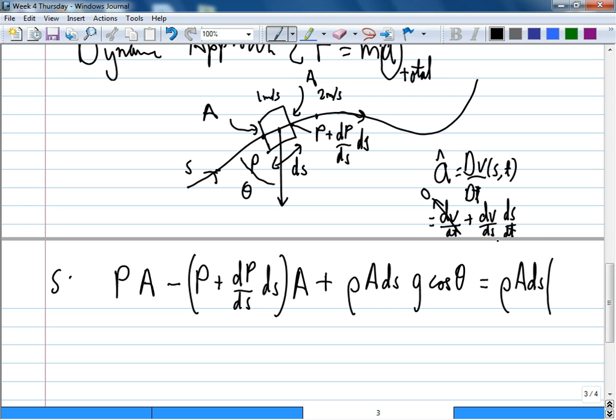From an observer's point of view, everything is steady. But from the fluid particle's point of view, if you were that fluid particle, you would feel that you accelerate. The observer looks, and every time there it's 1 meter per second here, 2 meters per second there, steady state. But if you were that piece of fluid, you would feel your speed go from 1, to 1.2, 1.3, 1.4, until you reach 2 meters per second. That's captured in here, so you need a force to capture that part also.